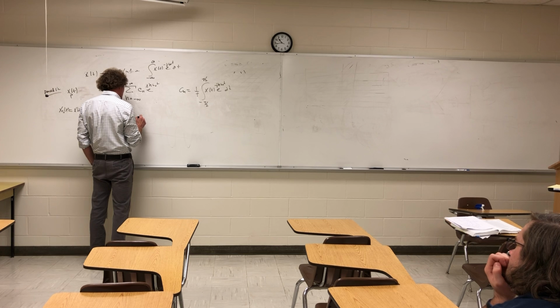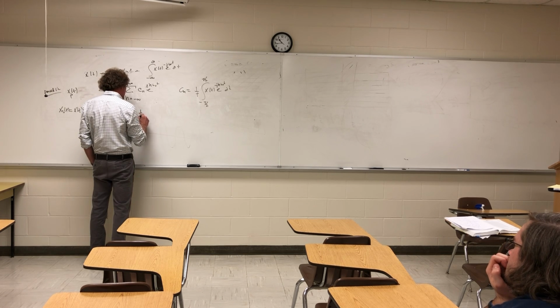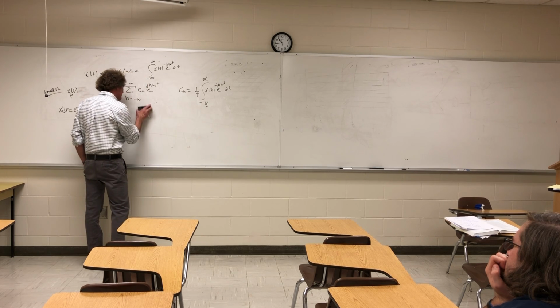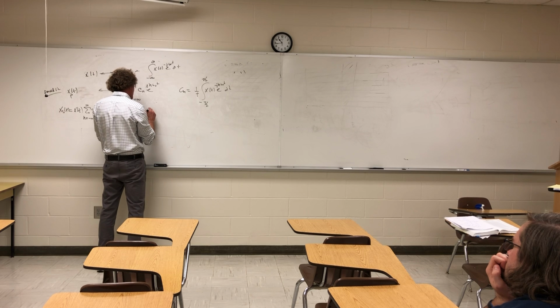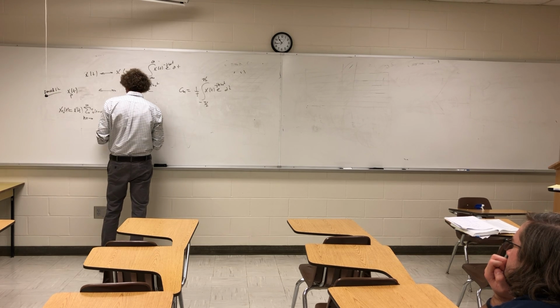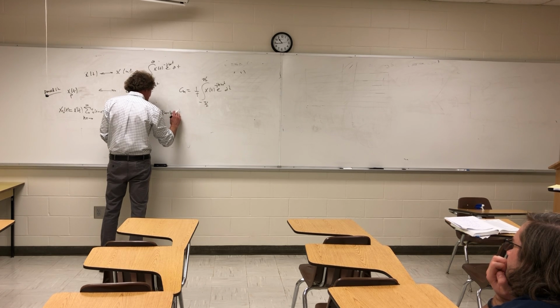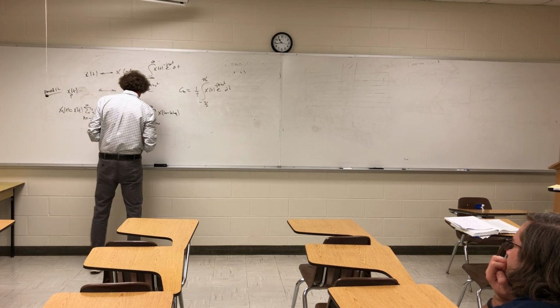Now we're going to get 1/2 pi times, and when we do this, I think you remember this, it's actually going to be an infinite series now. And you can use k if you want, from minus infinity to infinity of X of omega minus k omega S, the sampling frequency, and you have 1 over T out here.